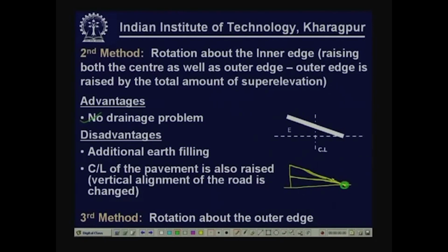However, this method has its own disadvantages. First thing is, earthwork is no more balanced. So, additional earth filling is required, because we are rotating the pavement now with respect to the inner edge.